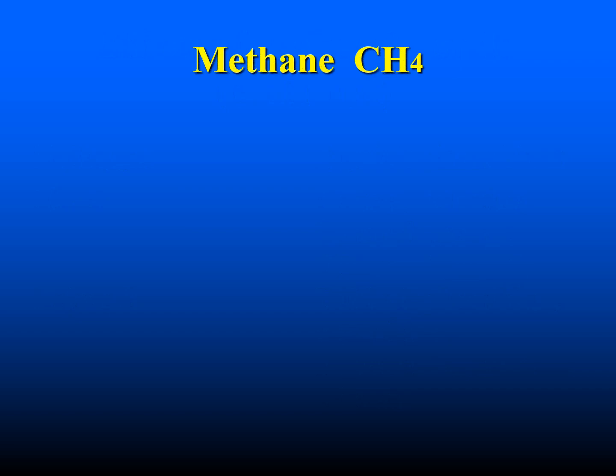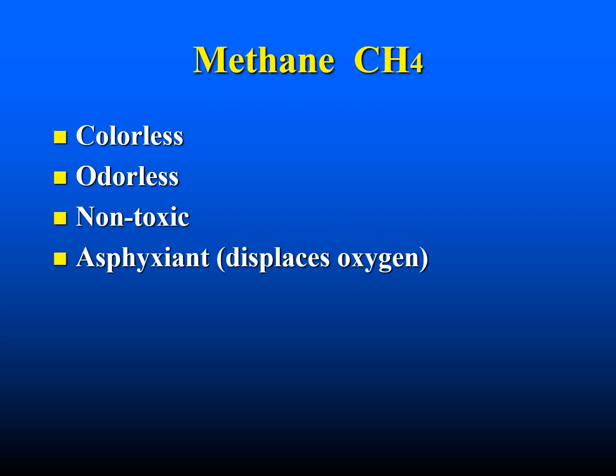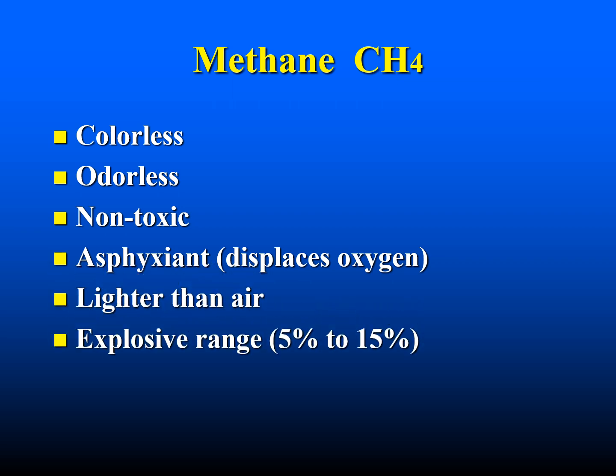Another target gas is methane. It is colorless, odorless, and non-toxic. It is an asphyxiant, which means it displaces the oxygen in the atmosphere. It's lighter than air, and it has an explosive range of 5 to 15%.